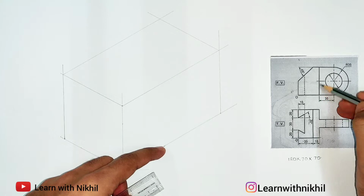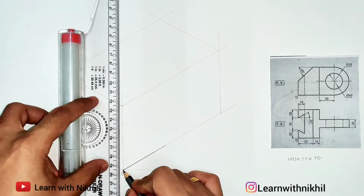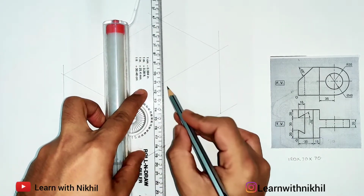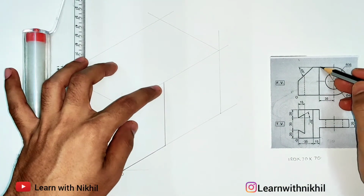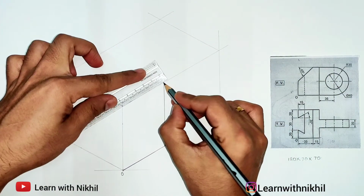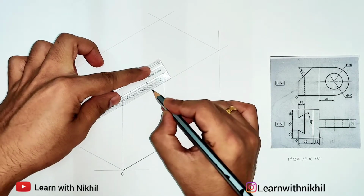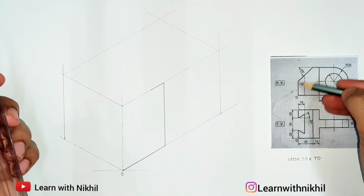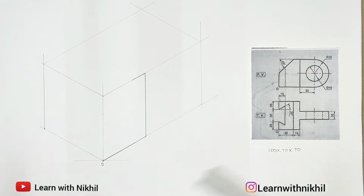Now moving towards this part, here you have a height extension, that is a straight dark line. So I'll draw this line. As there is a bend from here, you then have an extension forward of 15 millimeter. So from here 15 millimeter, make it dark. Now from here we have a slant line, we have an angle over here. So how to draw it?